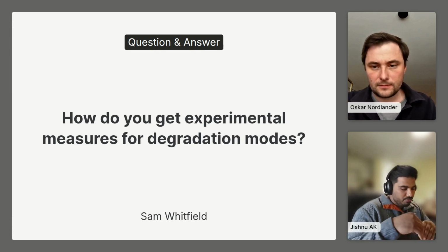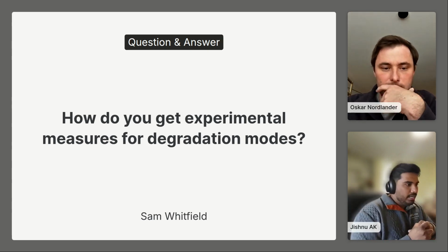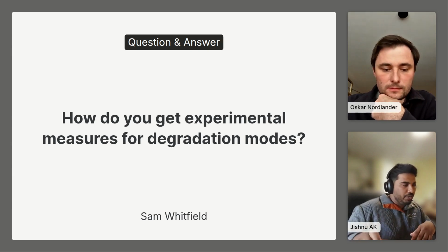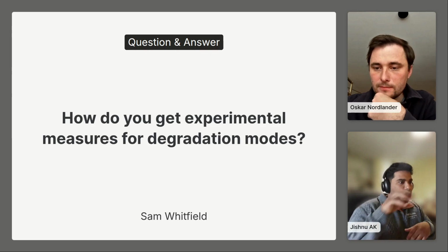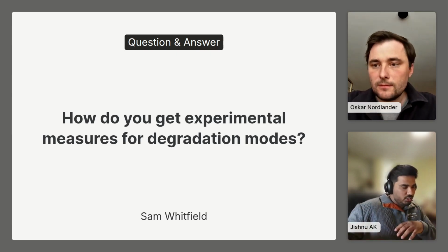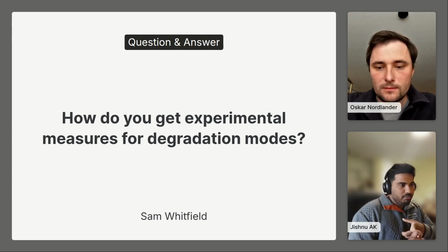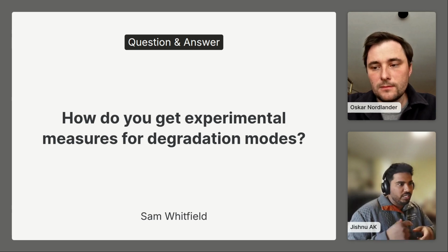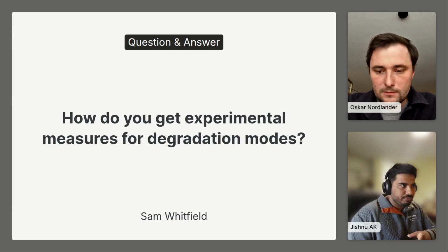So what are the stoichiometry values of anode and cathode at a fully charged full cell and fully depleted full cell. We do this at different stages of aging. If we get POCV data from the full cell testing at different stages of aging, we get the stoichiometric values at those stages. From that, we can calculate the total amount of lithium available in the cell now, and the capacity of each individual electrode, which we then compare against the beginning of life values to get the degradation modes.